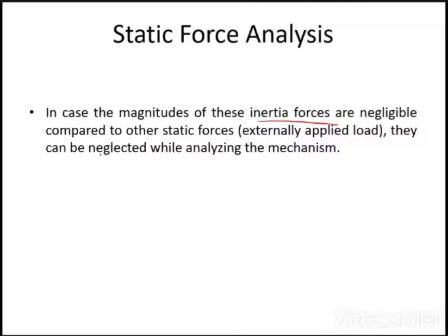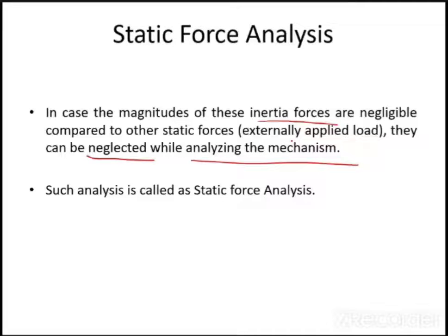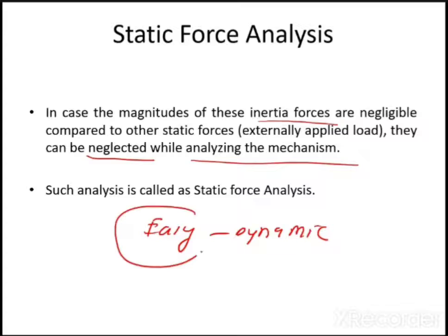Whenever you neglect the inertia forces while analyzing the mechanism, such analysis is called static force analysis. This analysis is very easy as compared to the dynamic analysis. Why? Because there is no change in the direction and the magnitude of the force, right?